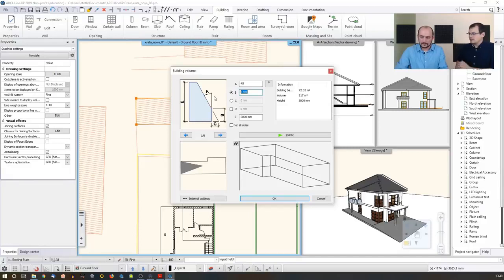What is the B value? The B value is basically the elevation, right? Actually, that's the vertical front of the building, so that should be like 6,000. Okay, let's go with that. 6,000. We are working with millimeters again today. And now all we have to define is the E value, the height of the building. It's kind of the maximum height, so even if the building shape would generate a larger building, that's the limit. So what will that be? Let's make it 9,000. Okay, just 9,000.